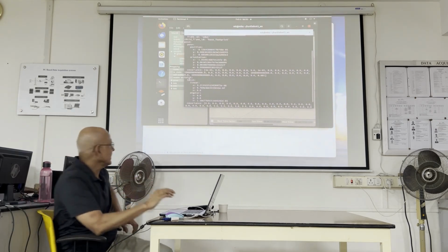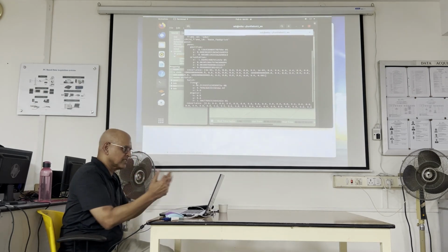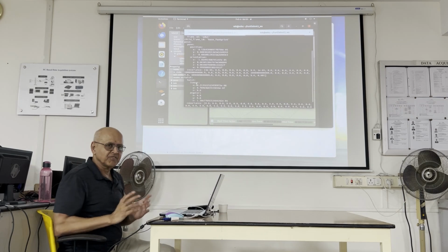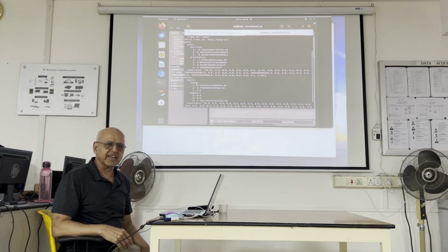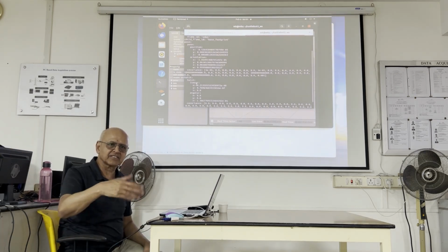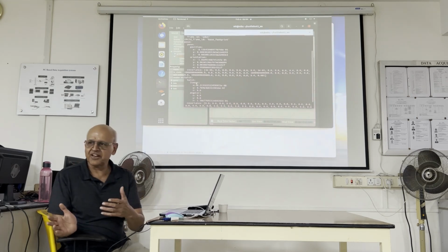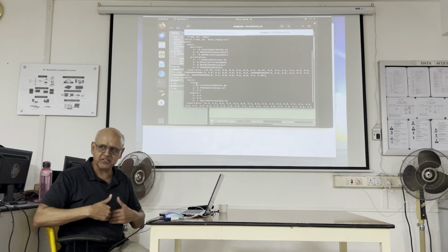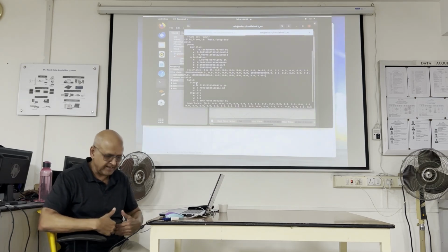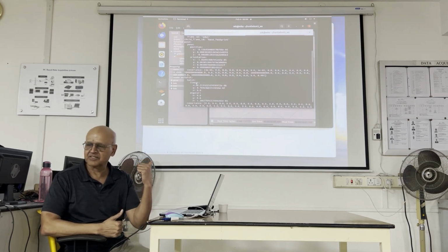T-W-I-S-T. And right now, it's saying the velocity of the robot in its own x direction. Now notice this, right? It has to be in its own direction. Because if you are running and somebody says your velocity with respect to the world axis is such and such, you'll say, okay, I don't know what it means, right? Because if you turn, that's going to change. So everybody wants to know their velocity with respect to their own axis, right? You can imagine an axis embedded in your stomach.